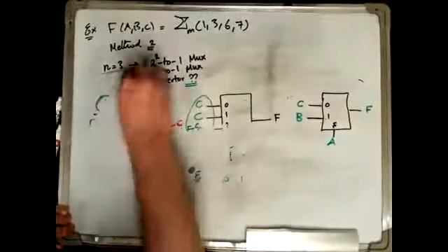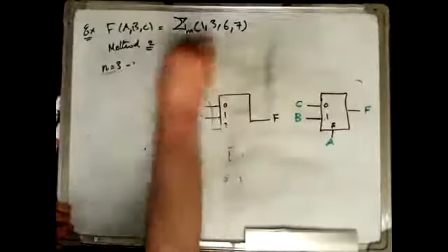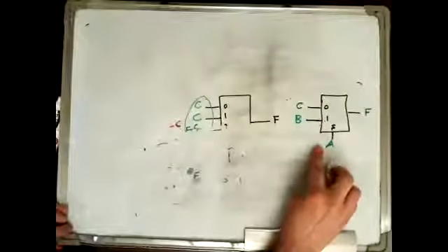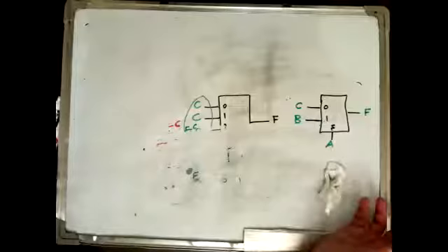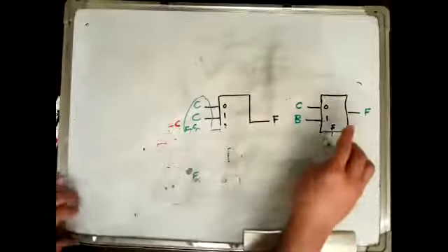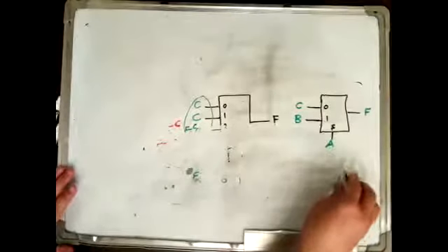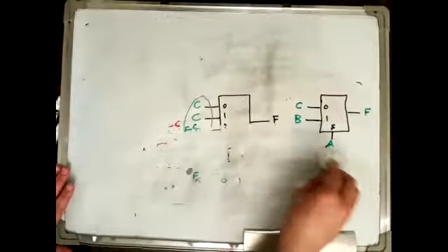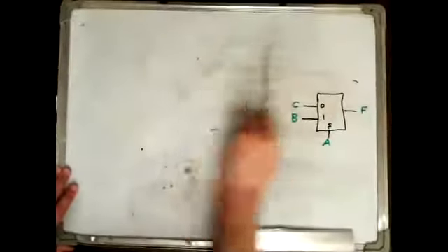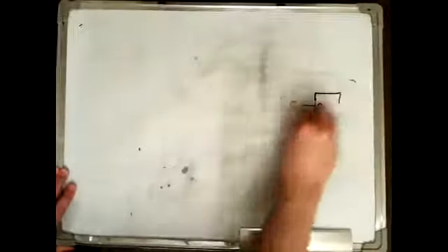So this is method number 2 and method number 3 and so on. Of course, we can't reduce the size of the mux to a 1 to 0 mux. There is nothing like this. So the smallest size we can go for is this. However, if we have a function of 5 variables, we can go from a 32 to 1 mux down to a 2 to 1 multiplexer.